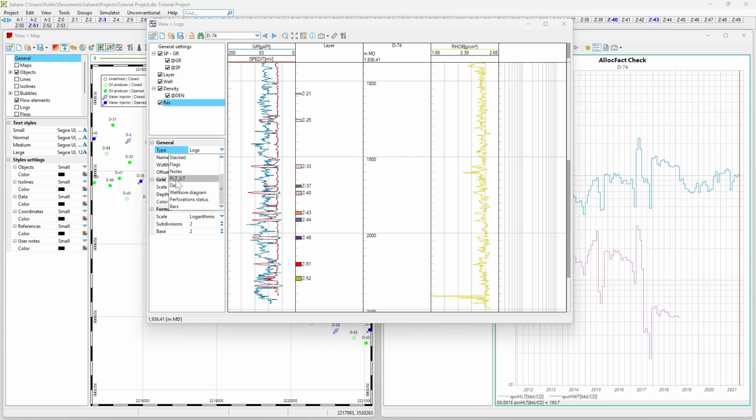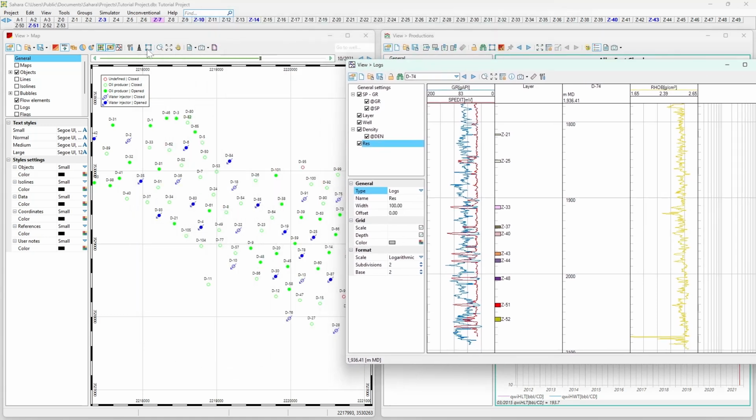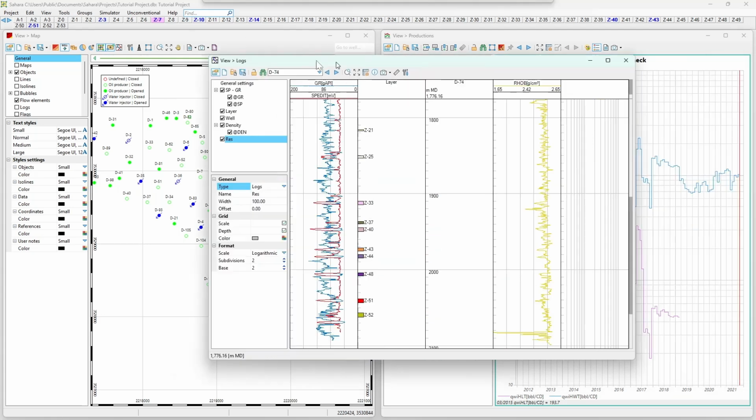Then here we can use this kind of tracks for showing PLT or ELT information. This data will show data at the layer level, which can be, for example, petrophysical data or monthly production, daily production, or for example sporadic data. For all those that are date dependent, for example sporadic data or monthly productions, not petrophysical data because petrophysical data is not time dependent, but for all the other ones, the date that will be considered for this data is going to be the one that is active on this slider, on the date selection slider.